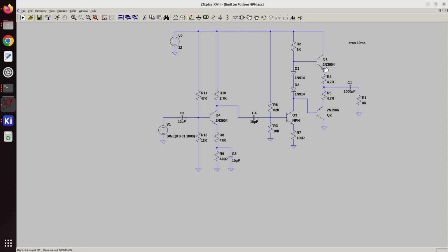But you can no longer turn this guy on, because best case you've got 12 volts here. If 12 volts here, this transistor is off. So in reality, you need a higher voltage here to turn this transistor on. So you can't get rail to rail. Now we definitely don't want rail to rail with 2N3904, 2N3906, and an 8 ohm resistor, or we'll have rail to rail smoke. But it's just to understand it more than anything.